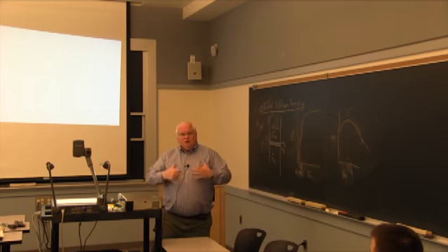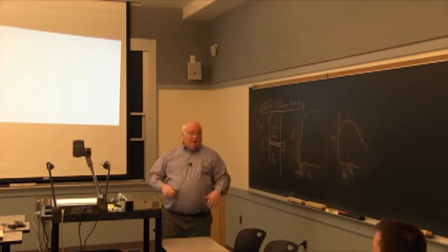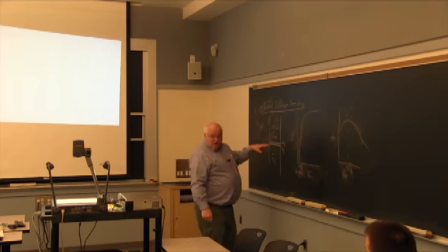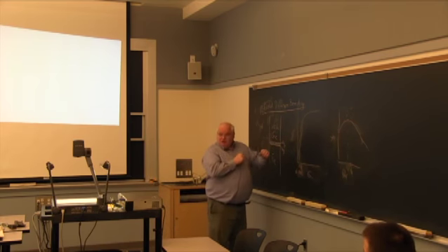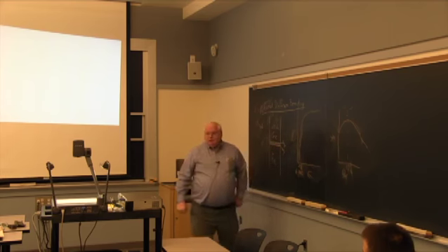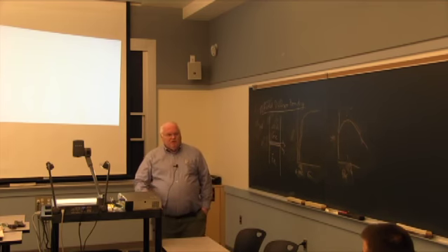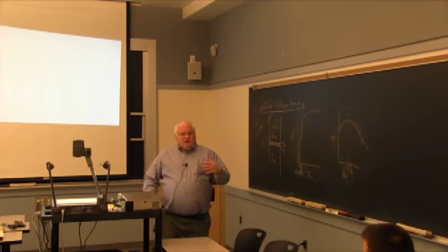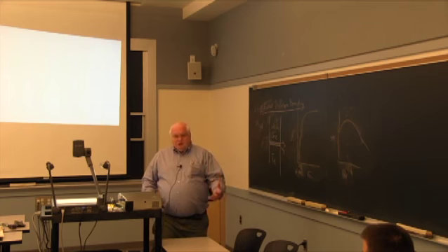Okay? And it won't yield. Now, it may not be very good in fatigue, and it's terrible in shear, okay? All because you got this soft inner layer in between here. But in pure tension, when you pull this in tension, you set up a triaxial stress state in that very thin joint, which can take something that has a strength of 10 or 20 KSI, and it can appear to have a strength of 100 KSI, okay?